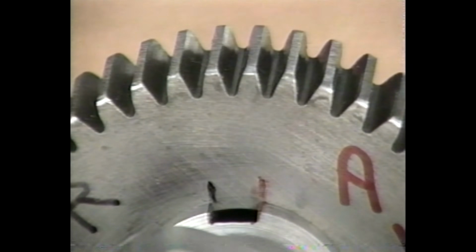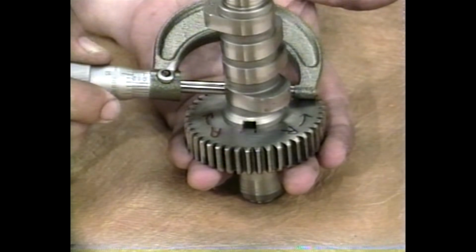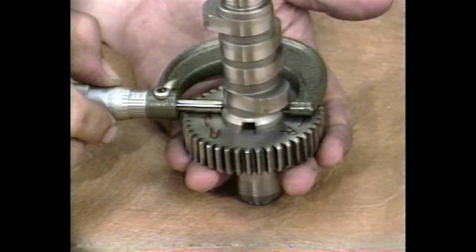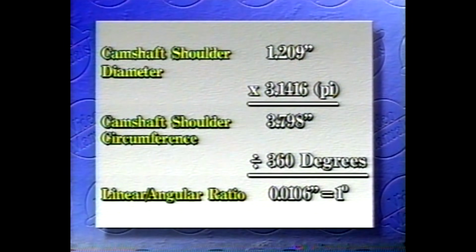Next, we must find the equivalent linear distance that we must rotate our drive gear on the camshaft to achieve the correct valve timing. Using a 1 to 2 inch outside micrometer, we measure the diameter of the shoulder behind the drive gear to be 1.209 inches. Note that this diameter will vary from cam to cam. Multiplying the diameter by pi, 3.1416, gives us the circumference of this shoulder equal to 3.798 inches.